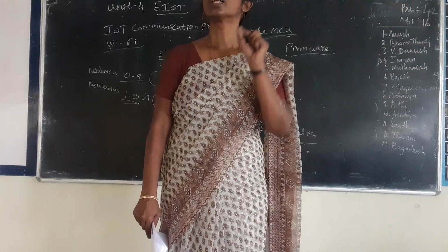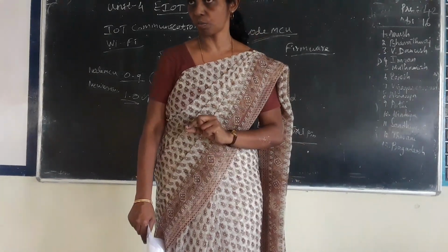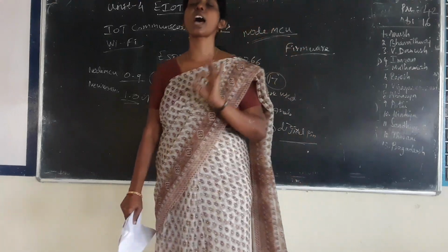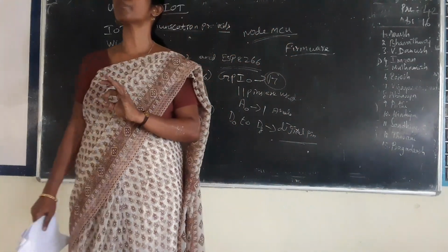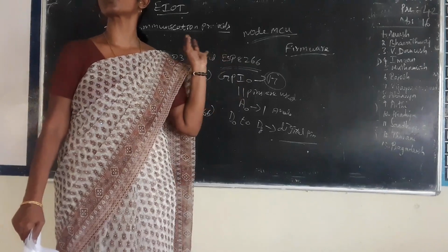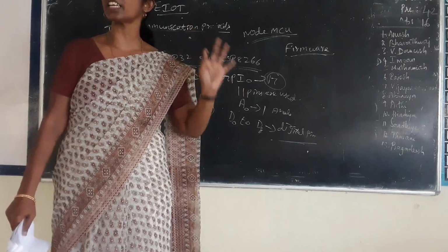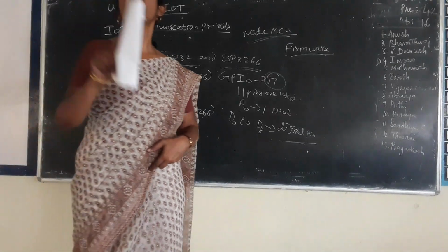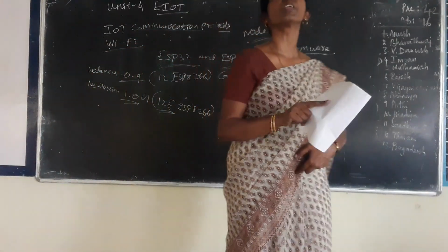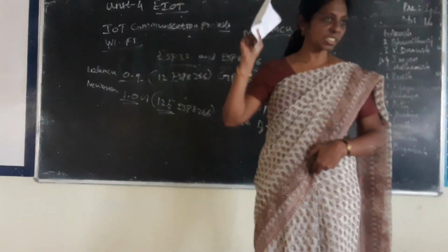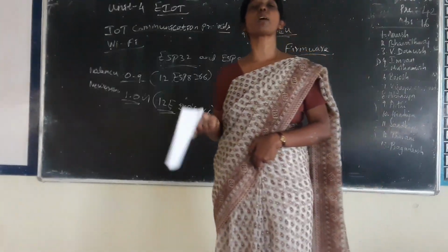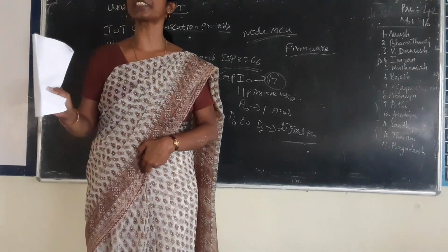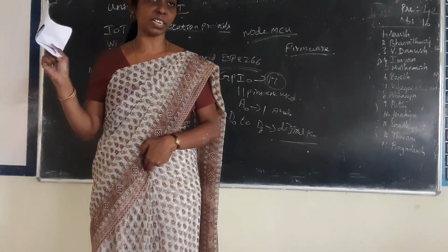If the board is not selected, the program will not upload. So whenever you are using an Arduino, you have to remember the port numbers, the tools, and the board you are using, and select them before uploading. You can type the program, no problem, but before uploading you have to check all this, and only then will it upload. Otherwise it will show a file directory error or other types of errors.